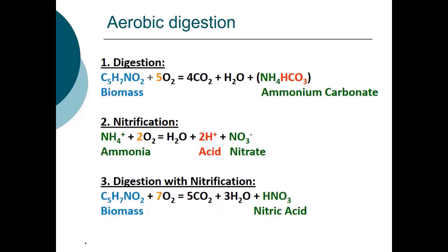When we're looking at aerobic digestion, notice here, we're adding oxygen. So what are we doing here? We're converting that biomass to CO2 and producing ammonium ions.